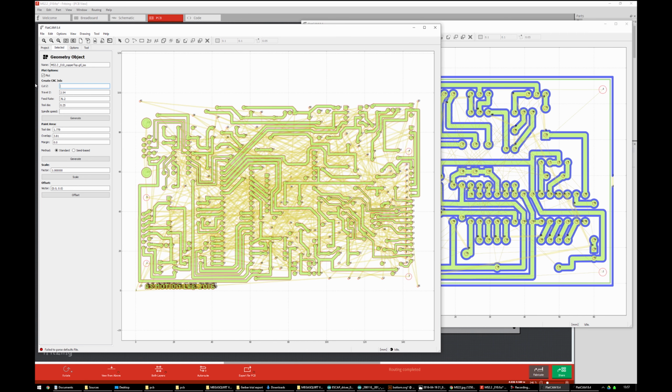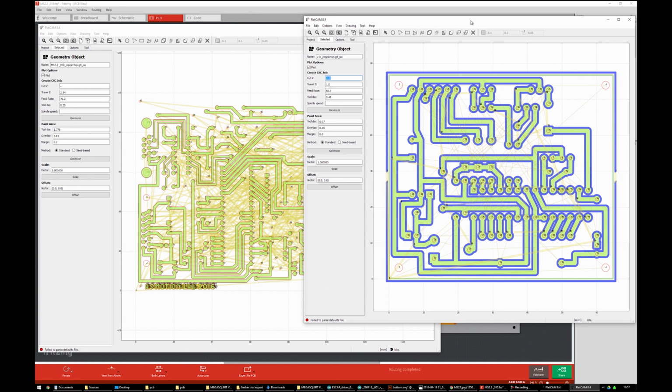Obviously, this cutting depth is more of a guide than a rigid setting, because what happens is if your board is not completely flat, you need to find the highest area of the board, and do a sample cut and see how deep you need to go to pierce through the copper layer. You need to go deep enough to pierce through the layer, but not so deep that it causes full-on holes in your board.